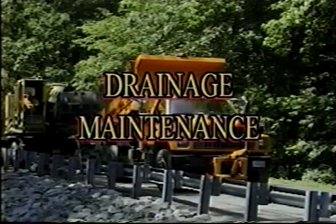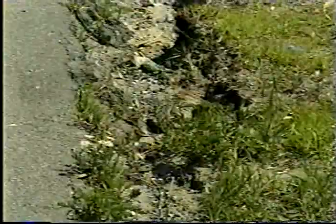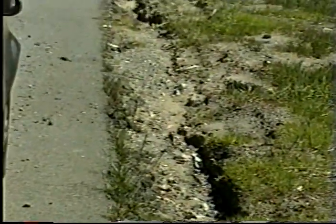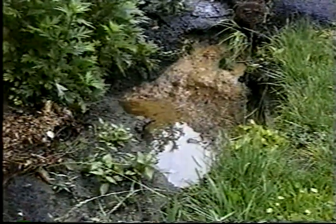Money spent on the maintenance of drainage systems directly affects the long-term cost of all roadway maintenance by slowing deterioration and reducing the scope of future repairs. Water, if not removed quickly, will either lower the supporting ability of the subgrade material that supports the pavement or will simply wash it away. When water is prevented from saturating the subgrade either through correction by underdrains or prevention by a properly functioning drainage system, the investment made in the street is protected against premature loss.